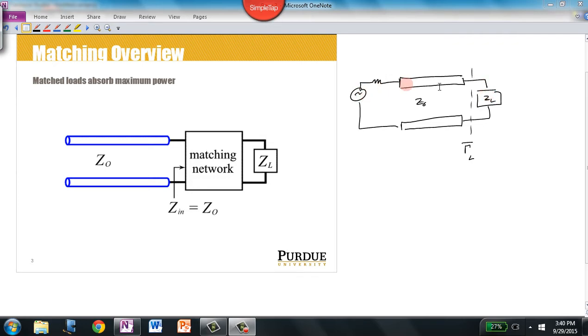What we're saying is that maximum power transfer to the load occurs when all the circuit is matched, when ZG equals Z0 and ZL. But often we don't have control over the impedance of the load. That's often a parameter of the load that we can't control, and we can't just always make custom cables. It's very common to find a 50 ohm cable or a 75 ohm cable, but finding cables of other impedances, they're very rare. And so the situation arises where we need to connect a load to a cable, and the load and the characteristic impedance of the cable are not matched in impedance.